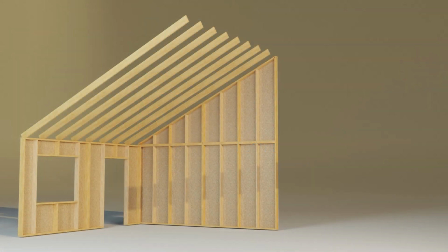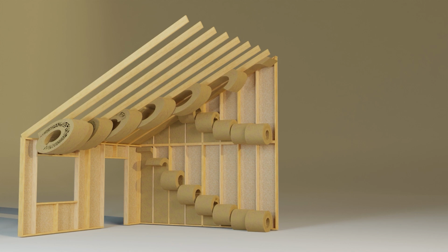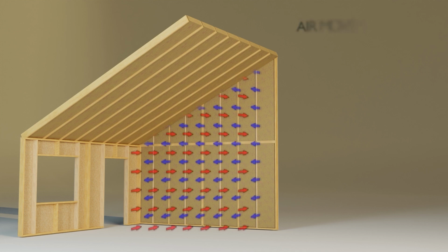The type of base construction chosen will have a significant effect on how complex the management of heat, air, and moisture movement is. If we begin by considering a typical timber frame structure, we can see that this build-up requires the mitigation of a number of issues. Firstly, in a traditional open panel timber frame, the insulation is fitted on site between structural timbers, and likewise either in the loft space or, as shown here, between roof rafters.